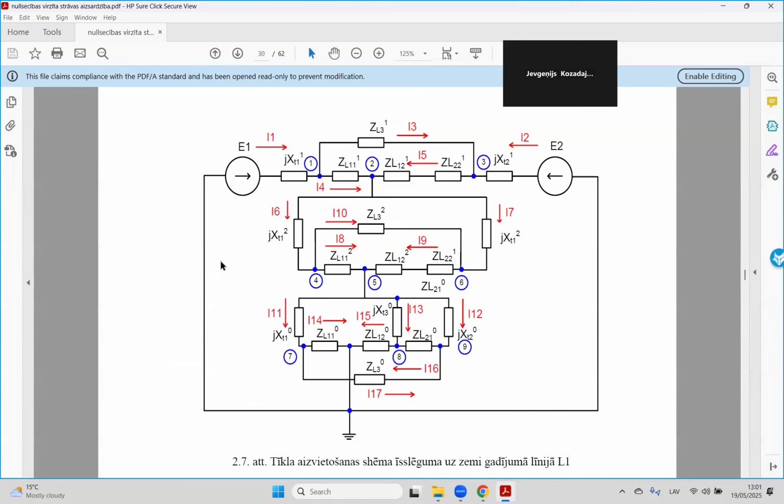For the transformer, the main part is reactance, the resistance is very small. That's why we very often replace impedance with reactance, because they're almost similar. Impedance is for lines. In this way, we represent the network, and we draw positive, negative, and zero sequence at once.